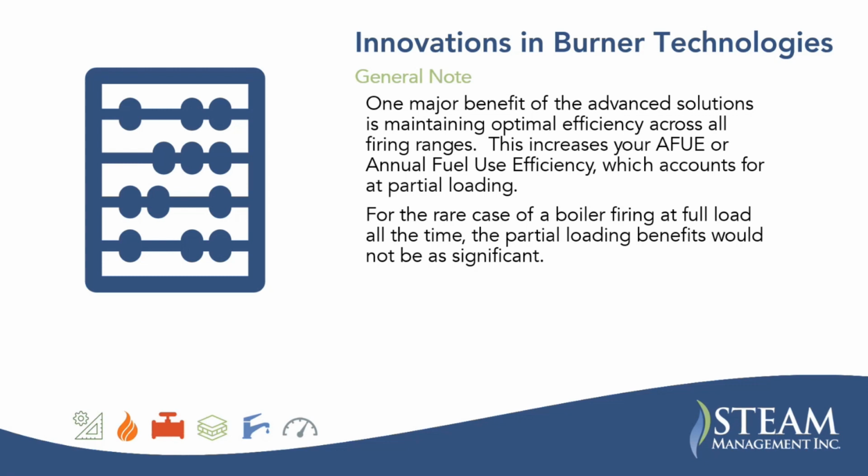You could get your boiler tuned to where it was burning at an optimal firing ratio, or fuel air ratio, getting optimal combustion, and you don't need all of this technology to get the same result.